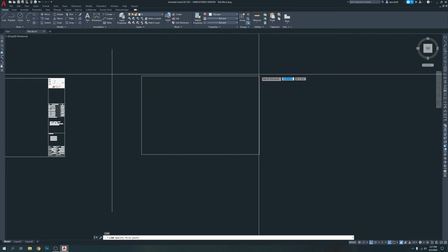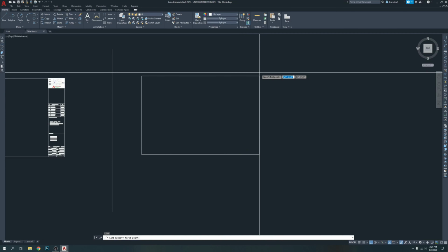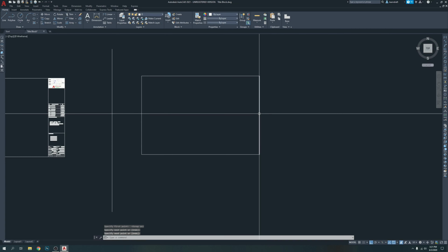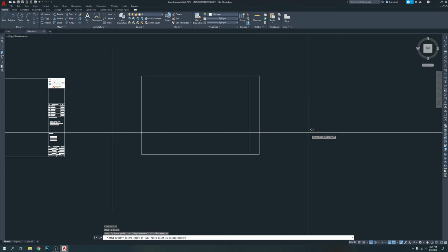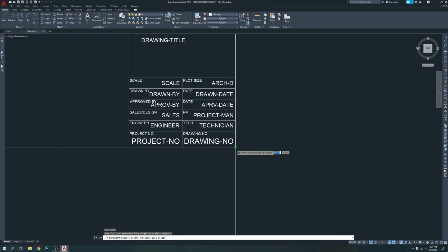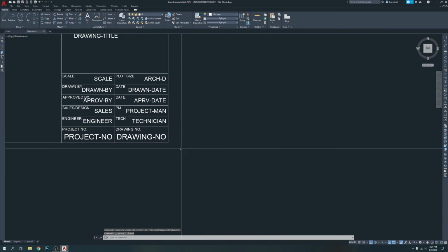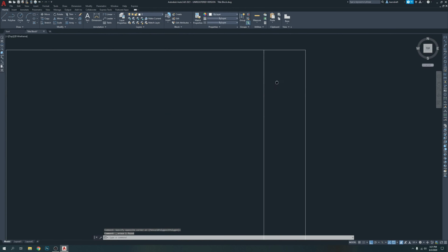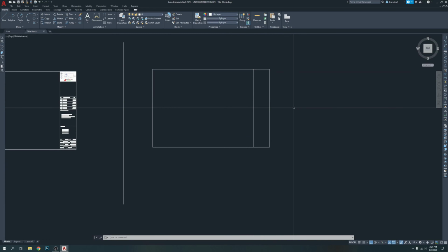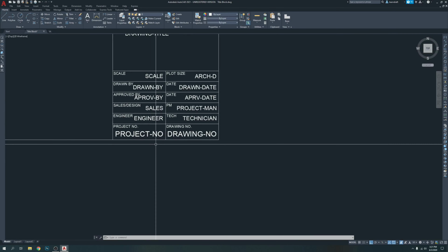Okay, so I'm going to create a line here. L, enter. My F3 is off, so I turn it on by pressing F3. Click, enter, click this one, move it. I think you move it 5 inches, so 5, enter, put 5. DLI, enter. Let's check how much I put there. 5, yes. So this is 5. We're good.